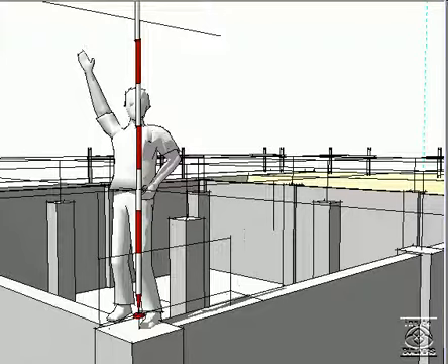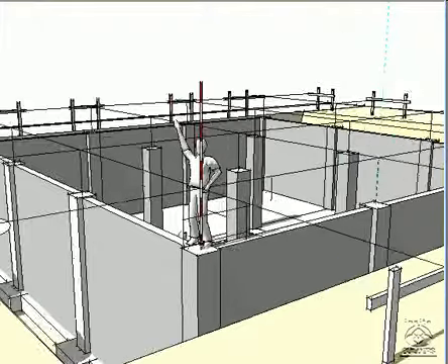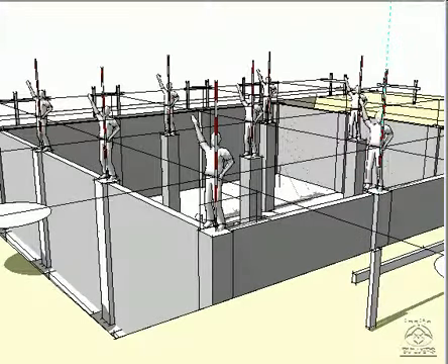The challenge is that the tops of all of these columns are slightly different. It would also be tough to put a surveyor out on the foundation walls and columns with any degree of accuracy, let alone safety. But there are string lines over the column centers. Keep in mind these string lines have been used throughout the foundation and basement construction in almost the same way that we're going to be using them for the raised slab. So they're a proven reference.